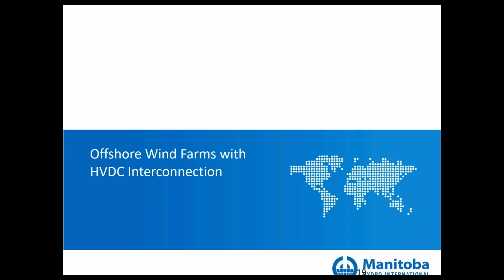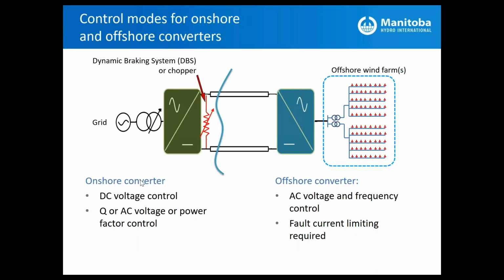Of course, you're dealing with an offshore converter station with more complex requirements than just a shunt reactor with variable taps. So this becomes a matter of the size and the economical and technical justification for building an offshore HVDC station. If that is justified, then we usually end up with this general scheme.